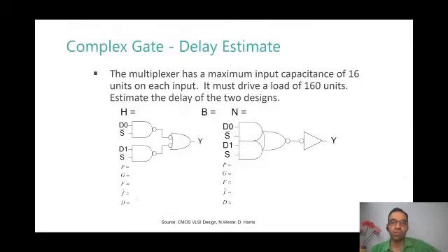Okay. So how do you estimate the delay of a complex gate? Like if I make a complex gate versus I make a two-stage implementation, what do you expect in terms of delay? Path delay, sir. So for this, the overall H, let us say, is 10. B is 1, there is no branching happening anywhere. And the number of stages is 2 in both the cases. So what would be the different delays? Can you find out by using a logical effort analysis?